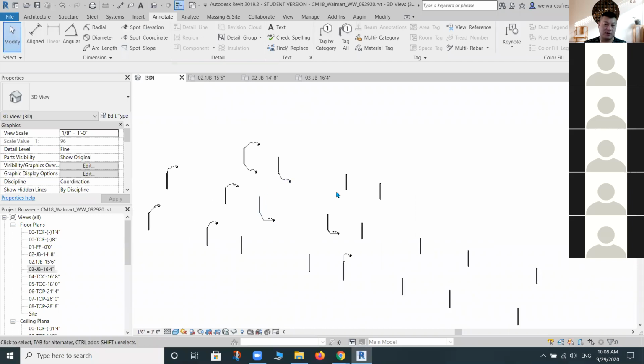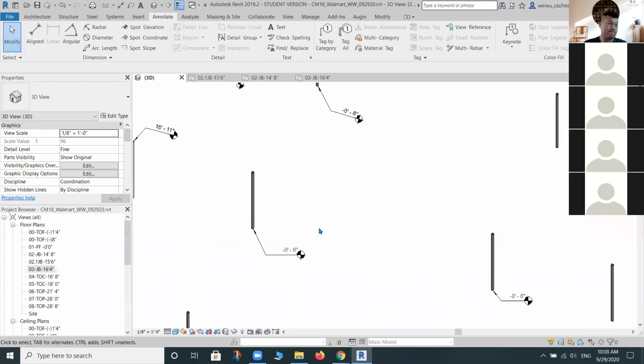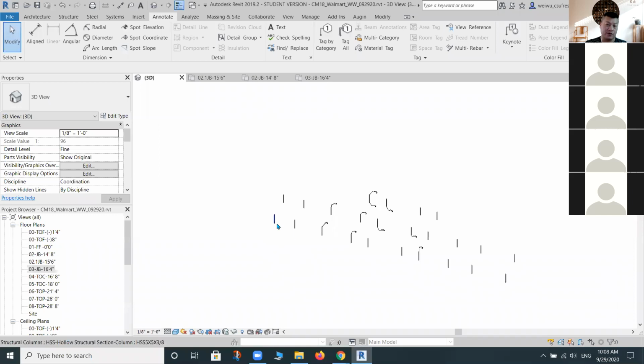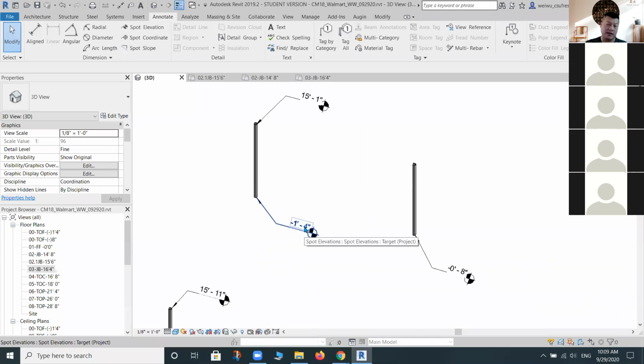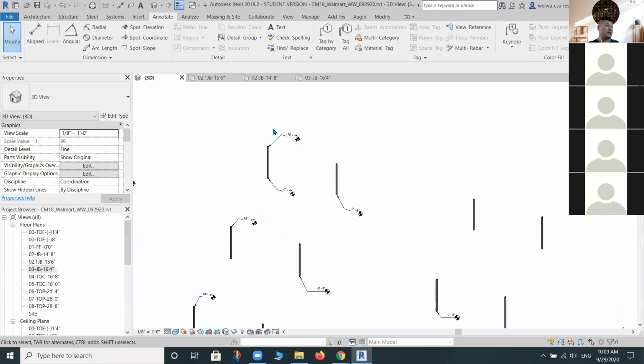Actually, all the ones on the second row, which is grid line B, are supposed to be -8 inches, because they're all considered to be interior columns, except for the front, which is grid line A, and on grid line C, you do have those two on the sides. They are exterior columns, so that's why they had our column depth at -144 inches. Okay. Anything else? Any other questions?